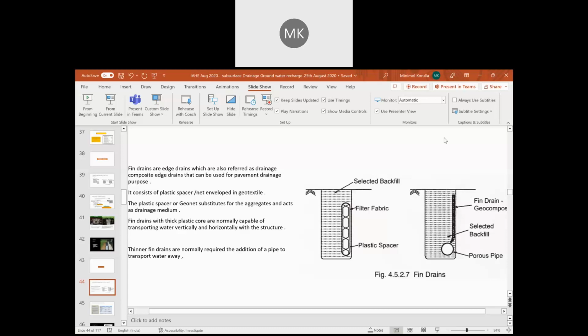Then IRC 34, we have seen a lot of things. We mentioned waterlogged areas, and for hill roads, how to give the toe wall, whether it can be a gabion wall or a dry masonry, but it should be permeable. All these are from IRC 34-2011. Then IRC 56-2011 is in fact a publication on erosion control, but it really speaks about how drainage and erosion control have to be given together.